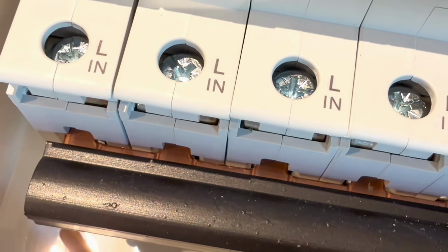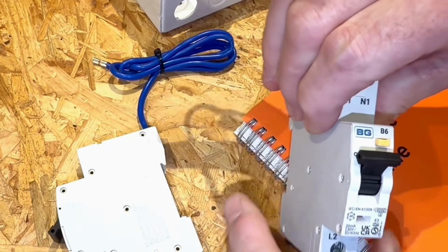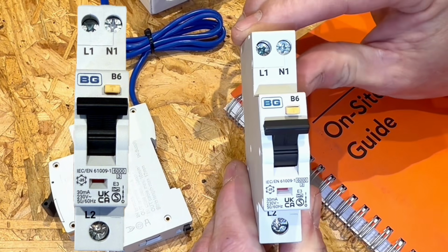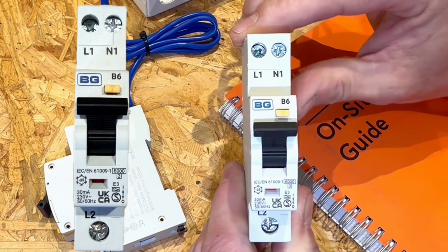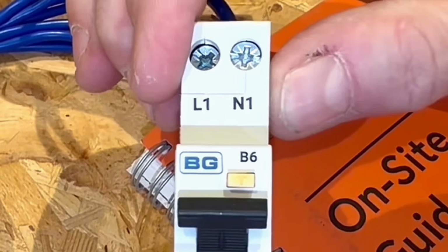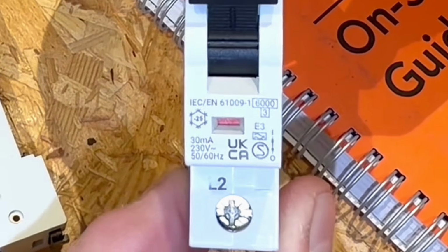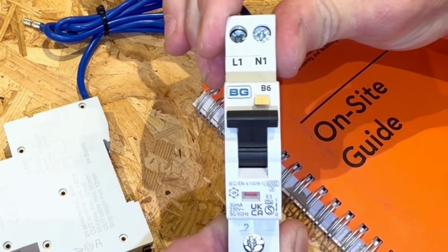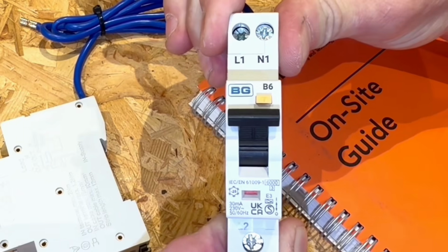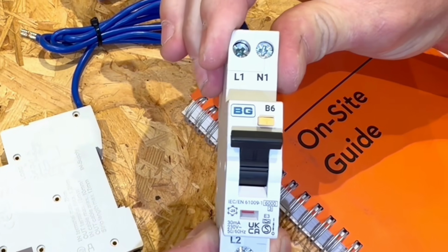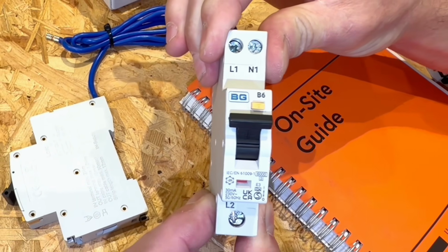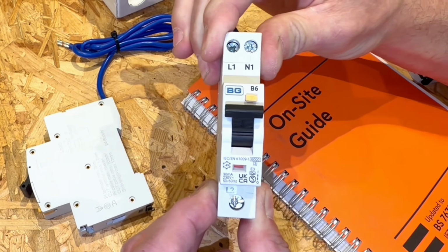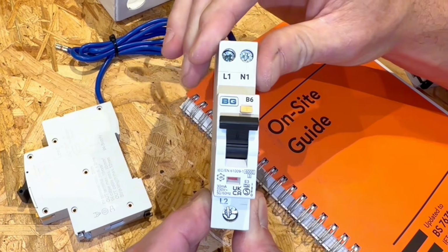Let's look at the next device and see what we can see here. Now we've all of a sudden got a very similar RCBO, with exactly the same layout. It might be slightly different in the positions of switches, etc. But now it says L1, N1, L2. Now you could be thinking this is in and this is out because that's the standard layout, but it hasn't defined the device as the supply coming in or the supply going out. Therefore, this is a bi-directional device. They also sometimes write on the device itself that it is bi-directional, but you can tell because it isn't labelled for its connections, the electricity can flow in both directions.